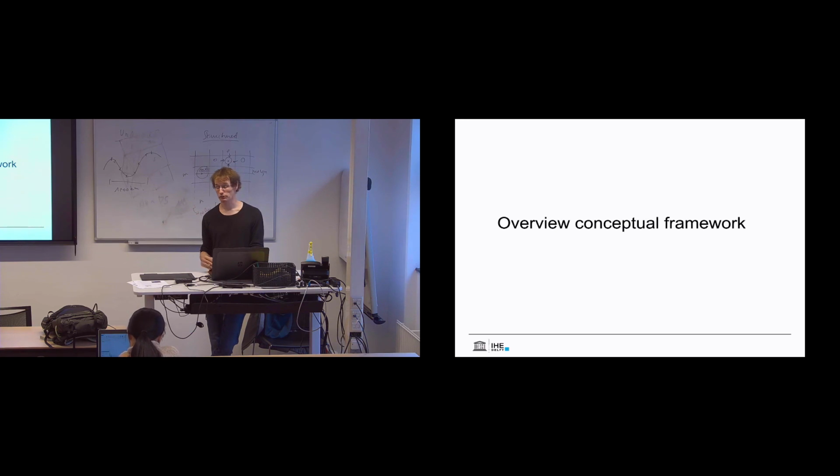But then again, also time steps. If you have, for example, a problem where the geometry is more or less fixed, so the chances that you will have to adapt the grid are fairly small, so building the grid is a one-time operation, and you only have to vary the boundary conditions or these different scenarios, then you could choose Delft3D, because if you design your model a little optimally, then you could probably use bigger time steps than flexible mesh.